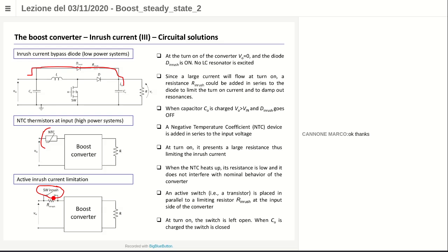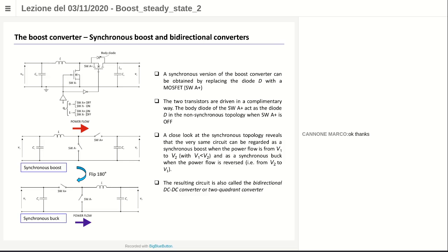When you are turning off the MOSFET, so you're opening the switch, the current flowing, the inrush current, goes through the resistance, which limits the amount of current. Then, when the output voltage reaches a specific value, I can put a signal to control this MOSFET to be closed, then short circuiting this resistance, okay? In that case, you have no dissipation, no problems about the efficiency of your system.